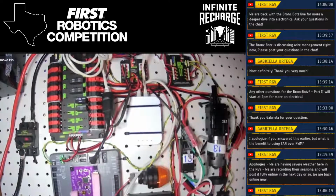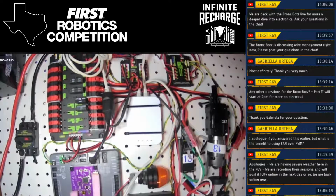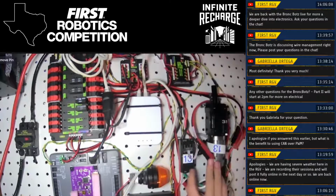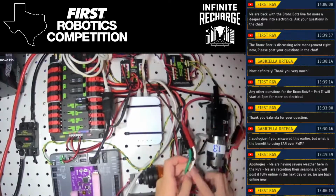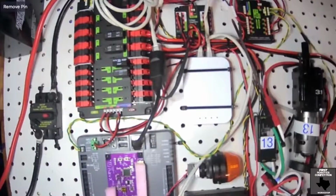The only other couple of things that I'm going to say is the label maker. I talked a little bit about that earlier, but when you start to wire anything, you're going to want a label on both ends of each wire. Let's just pull any wire. So you see this is labeled 13. This is motor 13. There's a label right here that says 13, and there's a label right here that says 13, that goes to motor 13. You just want everything to stay organized.